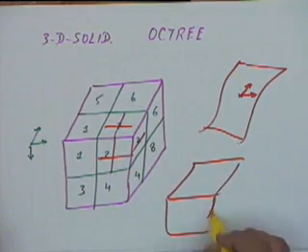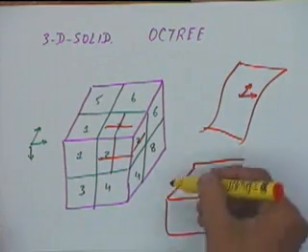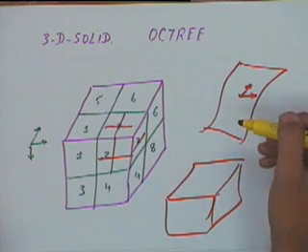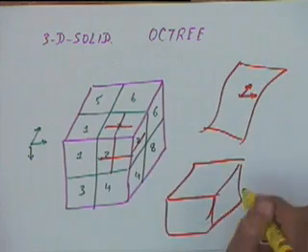If you want to represent a cube, we represent the equation of each of the faces and then say which half space is inside the solid, and the intersection of all of those will give us the final solid. But some kind of graph based representation is always used in which adjacency information is stored. That is the most commonly used form.